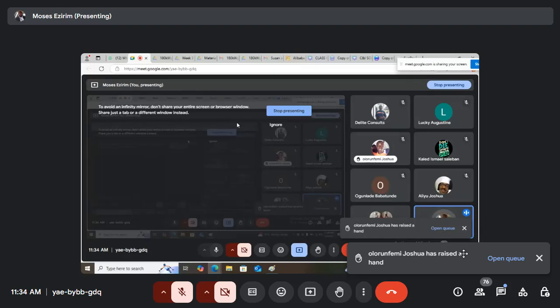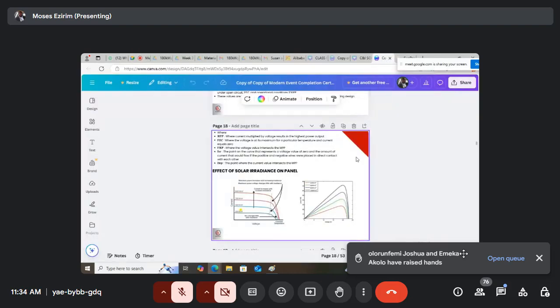All right. So I was able to say that based on my knowledge of irradiance, that irradiance has a higher effect on current. So if a particular panel from the data sheet has a current of, let's say, 12 amps or 13 amps, now around 9 a.m. in the morning, if I'm checking the current, I should be getting probably 2 amps, 3 amps.